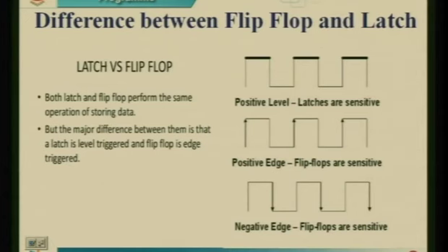So, you can see the difference here with respect to the edges. Latch versus flip-flop, I have considered here both latch and flip-flop. Latches are sensitive to the positive level. This is the positive level. With respect to this positive level, your output responds, and similarly flip-flops are sensitive to the positive edge.